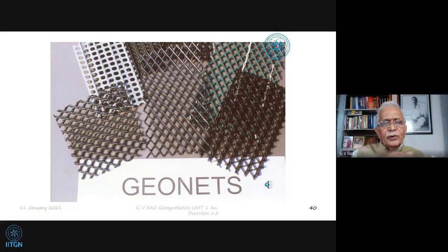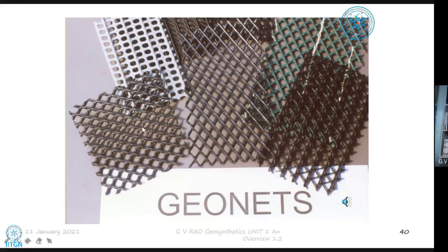It's going to be prevented only by the friction between the aggregate, that means between the stones and the surface, again the stones on the surface. So it's only by the planar friction, happening in both directions. Now, this is not sufficient in most cases. So, to have better performance, we have these kinds of materials.